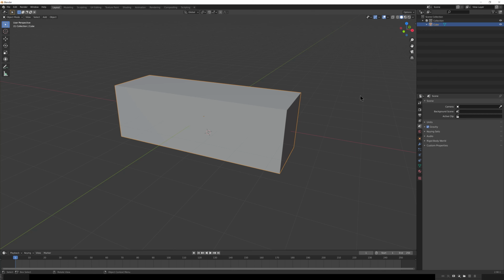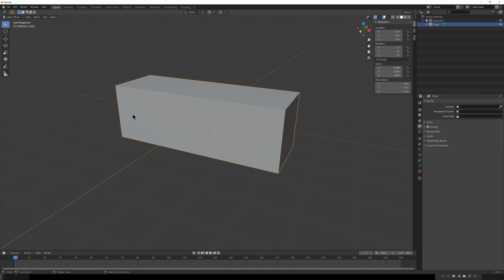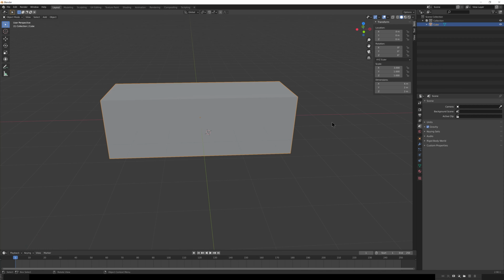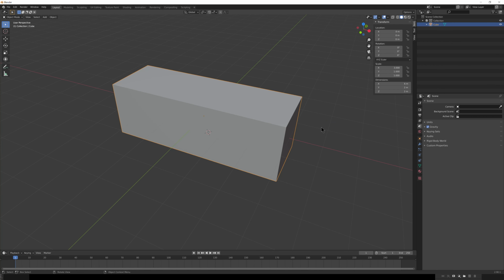If it's just a tiny bit off on either side, they could intersect and not line up properly on the grid. If we go ahead and hit the N key on our keyboard, we can go ahead and see the different sizes. I'm going to make sure that's exactly 3 in this case. Now I know my object will span 3 units in that direction, and if I'm using snapping later on in my program, if I set that to some interval of 3, say 1.5, or even something like 1, I can snap it in discrete units and they'll line up perfectly each time.